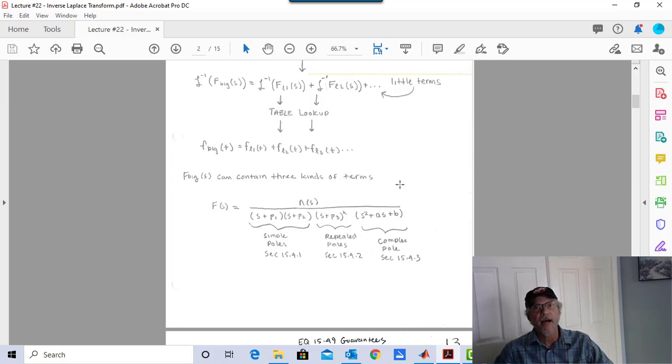So the poles would be up in the second quadrant and down in the third quadrant, if I have my quadrants right. But they'd be conjugates. And that's the difference between two simple poles multiplied together and complex poles. Just to digress a little bit, I will make comments as we go through the problems: whenever you see a factor like this, try to factor it, because it may just be two simple poles. And then it's a different animal than if this function had complex roots, complex poles.